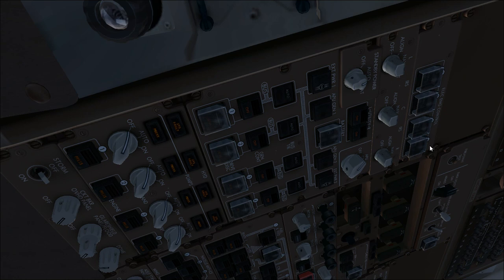Next one is the electrical panel. The electrical panel should be set and we can check. Standby power selector is in auto, okay, utility power switch powered, and so we have powered the utility buses and the galley buses of the aircraft. Battery switch is on and the off light is extinguished, and it's fine. Bus tie switch is in auto and the isolation light is out, and you can see it is extinguished, that's fine. Generator control switch is on and the off lights must remain illuminated. They are on and the lights are illuminated.